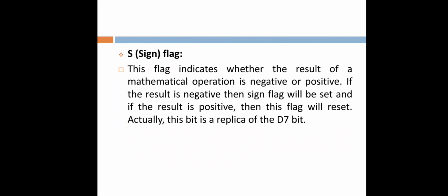Sign flag. This flag indicates whether the result of a mathematical operation is negative or positive. If the result is negative, then the sign flag will be set, and if the result is positive, then the flag will be reset. Actually, this flag is affected by the D7 bit of the accumulator.